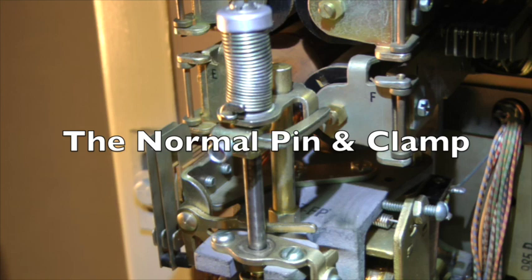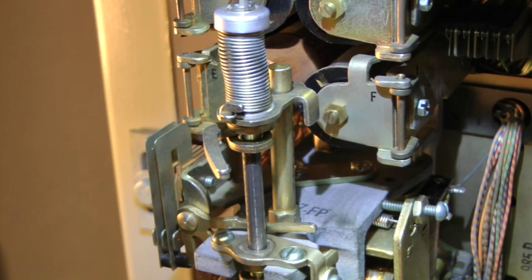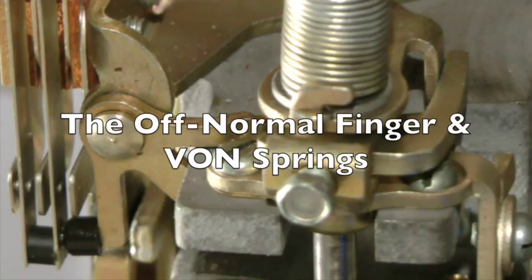The clamp just below the shaft spring bracket is called the normal pin clamp, and clamped tightly in its jaws is the normal pin. The normal pin stops the anti-clockwise rotation of the shaft when it reaches its normal rotary position. It does this by the simple act of striking up against the shaft spring bracket. The normal pin has one other function to perform.